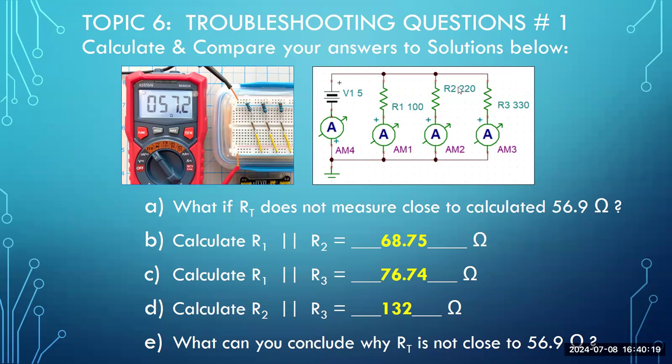Aha. These two are the only two resistances that we're calculating for a total in this case. And is 132 ohms, in fact, less than the lower of these two branches, which is 220 ohms? Remember, the 100 is not part of this calculation.